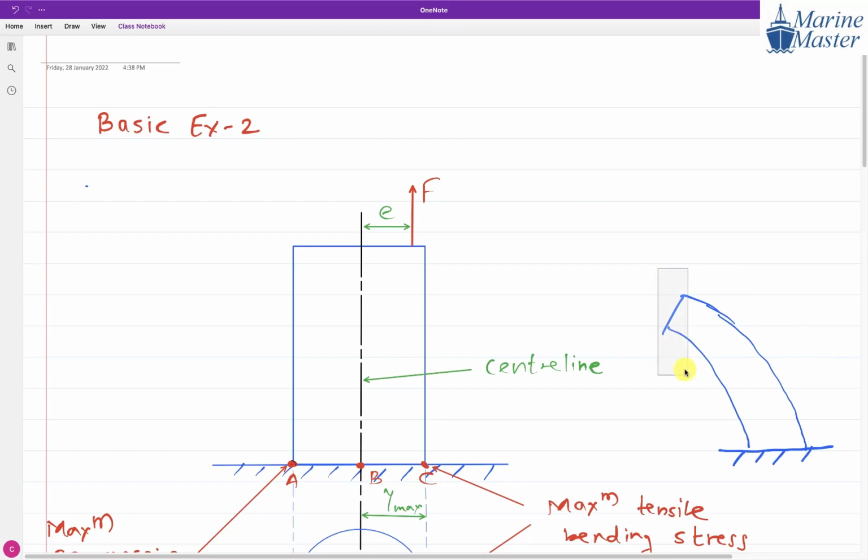It is not necessary that the shape of the beam after that loading will be like this. The beam may remain like that, or go in a different scenario, or not do anything. This is the shape showing only the effect of bending, nothing else. But actually, it is not only a bending scenario. It is a direct stress scenario also, expansion or compression. In this case, extension is there. It may be an extension scenario or a compression scenario. You have to see that one. Don't worry, you will understand more in our upcoming discussion while dealing with numericals, guys.